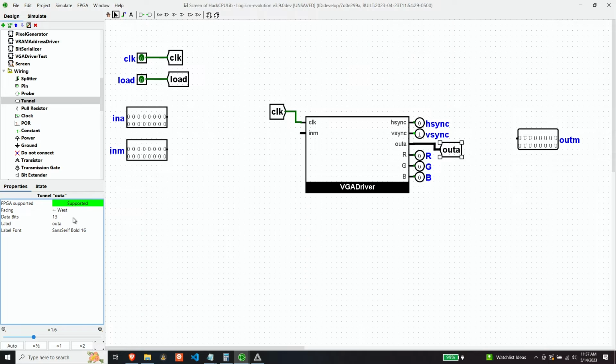My hunch is that the CPU will hog video RAM much less than the VGA driver ultimately would, because the VGA driver is trying to read RAM every 16 bits. And so an occasional dropout here and there, especially with our VGA rendering 70 frames a second, my guess is not going to be noticeable. Now, we're not trying to build a production system here, so it may be too annoying to be workable, but at this point, I think we're just going to go with it.